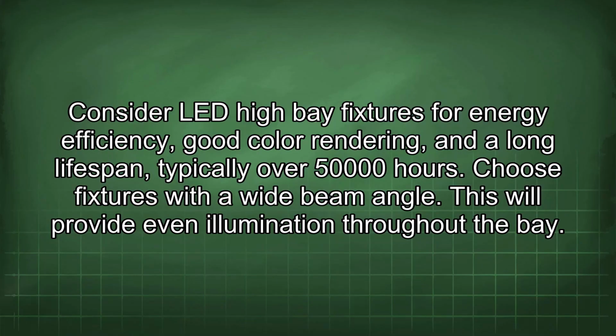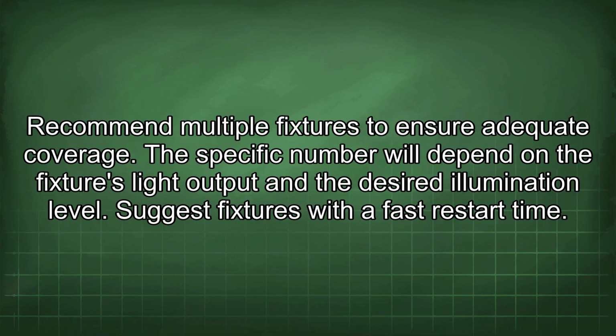Consider LED high bay fixtures for energy efficiency, good color rendering, and a long lifespan, typically over 50,000 hours. Choose fixtures with a wide beam angle. This will provide even illumination throughout the bay. Recommend multiple fixtures to ensure adequate coverage. The specific number will depend on the fixture's light output and the desired illumination level.